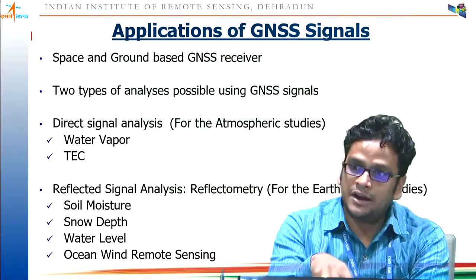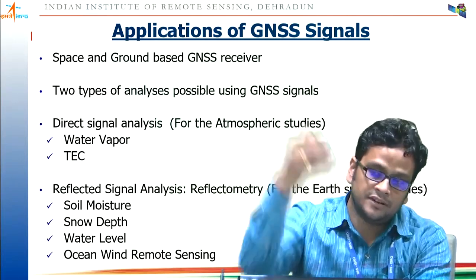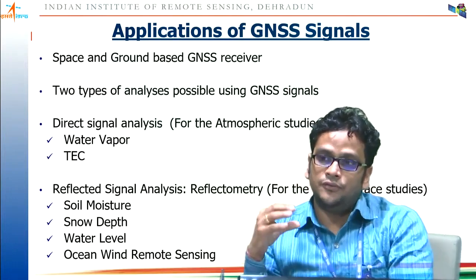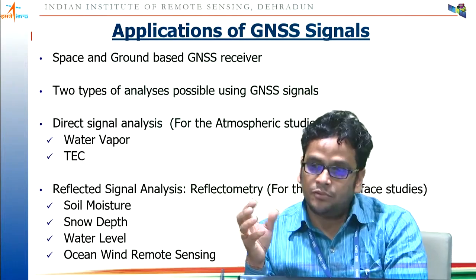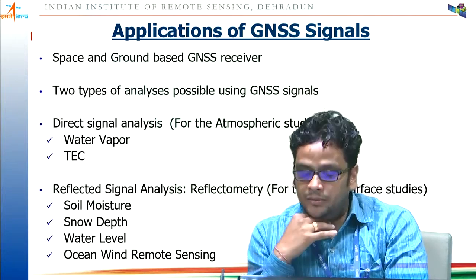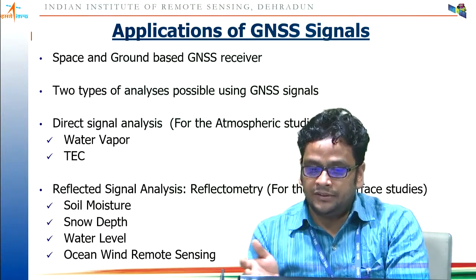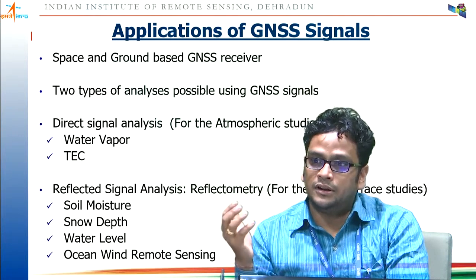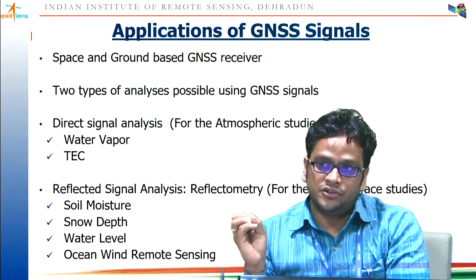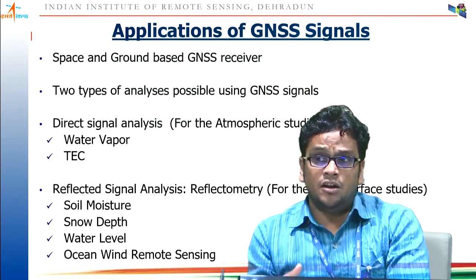So at a particular place, that's why we fix this receiver and receive the continuous data, so we can find out information about the atmosphere, basically the precipitable water vapor estimation, continuously at a particular point. Dynamic receivers we generally use for survey or positioning purposes, maybe collecting data for a shorter duration and then using it. Okay, these are basically the ground-based receivers.